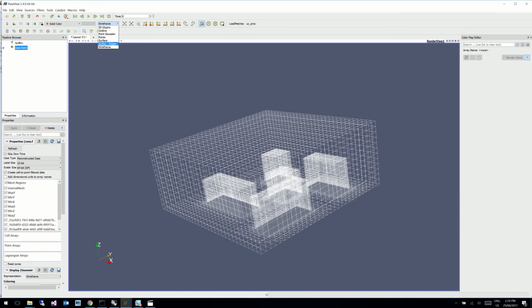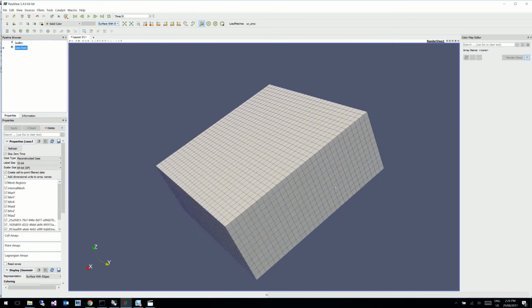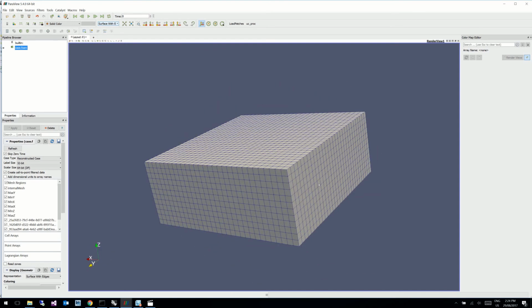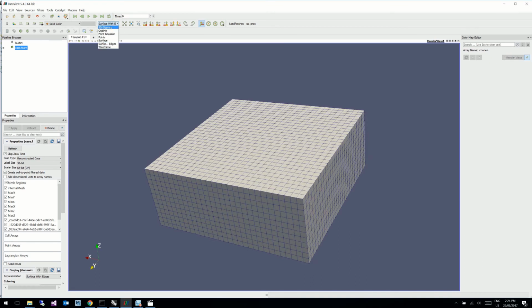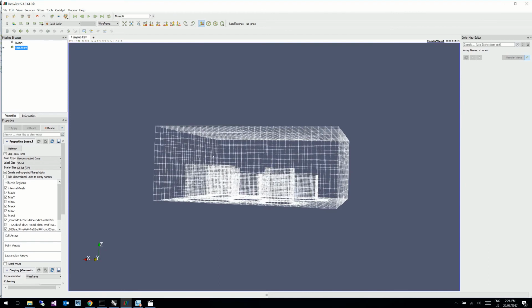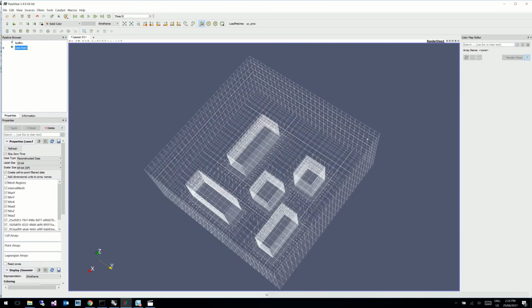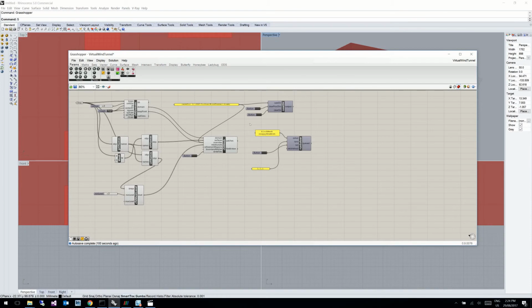The one thing you want to be sure of is that none of the cells on the outer surface have been subdivided. You need the entire mesh to remain subdivided inside. Otherwise you won't get a clean join between this mesh and the rotating turntable. So that's the meshing process, and it looks like we got an okay mesh, so let's continue on.